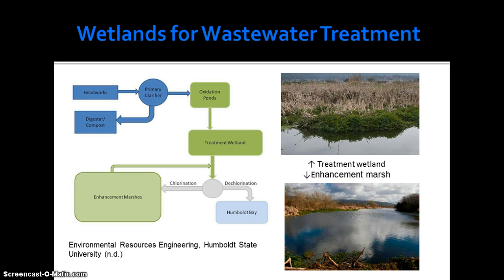The intent of secondary treatment, which uses a combination of natural physical and chemical processes through the treatment marsh, is to remove algae, reduce biological oxygen demand, or BOD, and remove non-filterable residues, or NFR, ammonia, total and fecal coliform, and nutrients such as nitrogen and phosphorus.